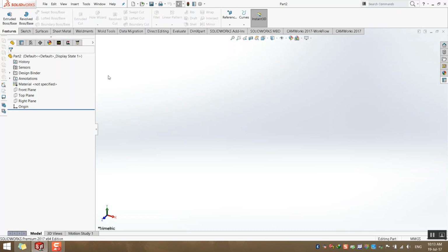This environment is divided into the drawing area, the history of all the operations or commands you do, and the tools that you use in drawing. Each command you do will show here, and its name will be in this area. This means your commands are arranged according to the steps you do, so you can cancel a step, delete a step, or modify it. That is a problem in CAD programs: if you need to modify something you did at the first step, it will be very hard to do that.